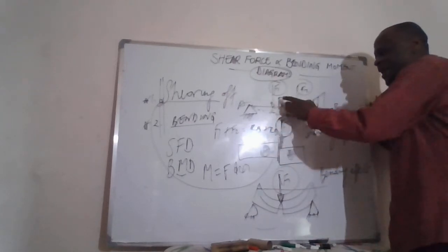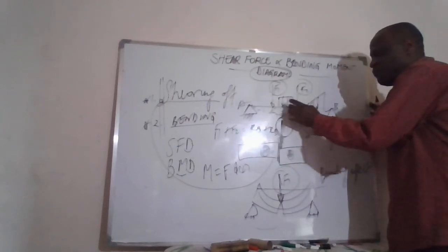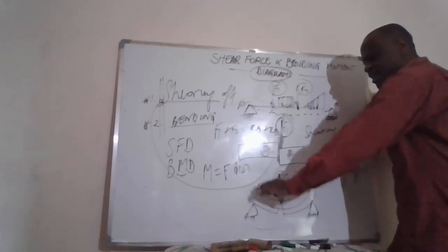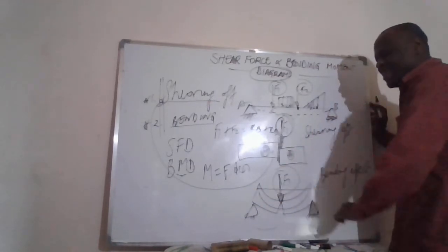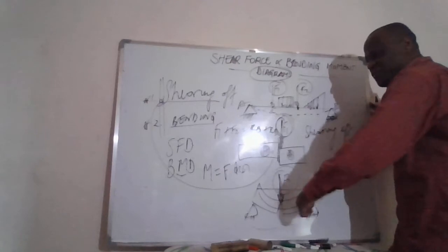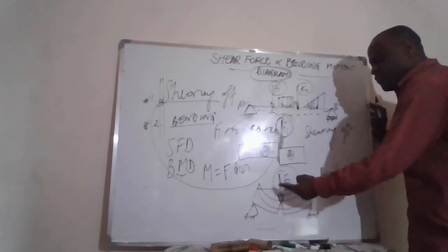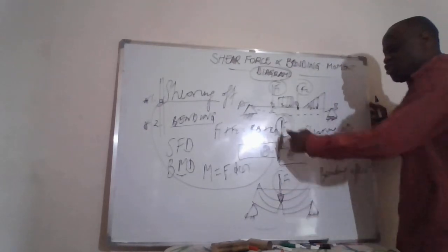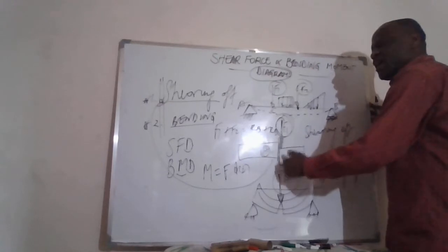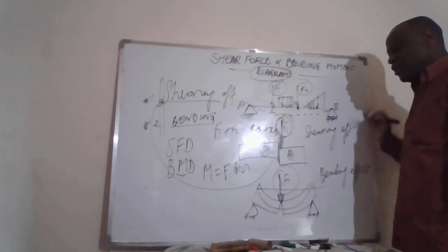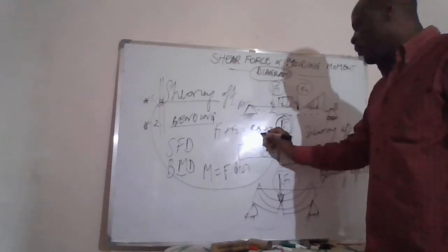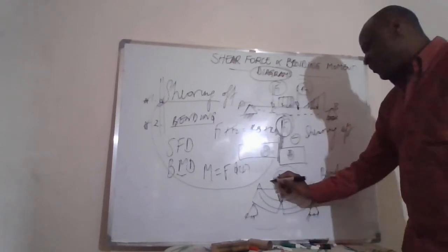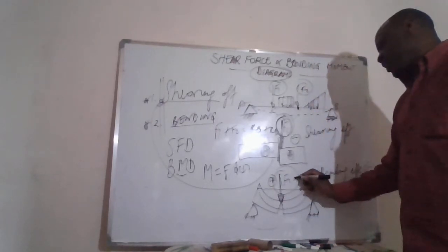Whenever loads are applied, be it a live load or a distributed load, this load will have a tendency of creating a failure by bending, if the bending is excessive. If the shearing effect is excessive, the shear failure can take place. And we have a shear force that can be positive or negative, as well as a bending moment that can be positive or negative.